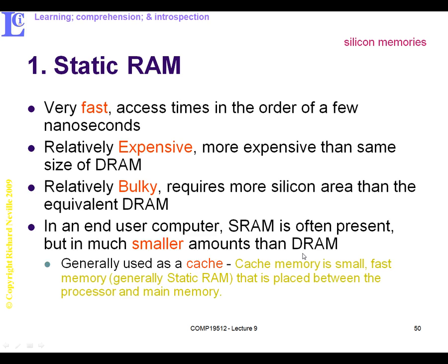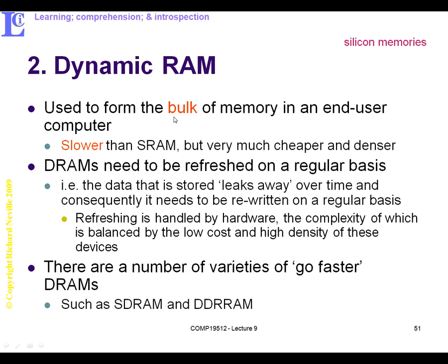Now that moves us on to DRAMs. DRAMs are really just capacitors. The strange thing about DRAMs as opposed to static RAMs is that you have to keep scanning them all the time to recharge the capacitors. So they're refreshed. There's a hidden refresh cycle underneath using the primary memory as DRAMs all the time, because the capacitors will always be losing charge. So let's go over these notes and explain what a DRAM is.